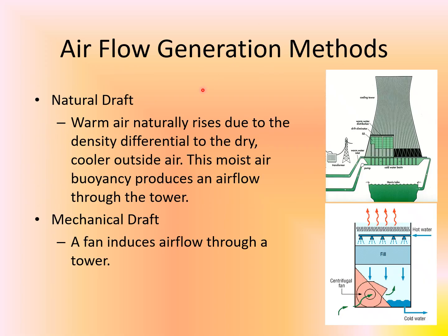Friends, there are two different techniques for airflow generation. First one is natural draft and second one is mechanical draft, and these two diagrams show them respectively. In case of natural draft, warm air naturally rises due to the density differential to the dry cooler outside air. This moist air buoyancy produces an airflow through the tower. Now, this is the airflow which is generated.